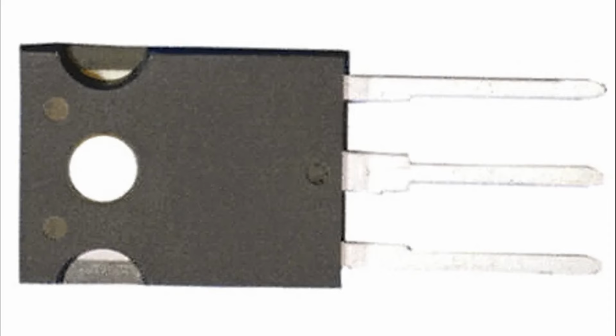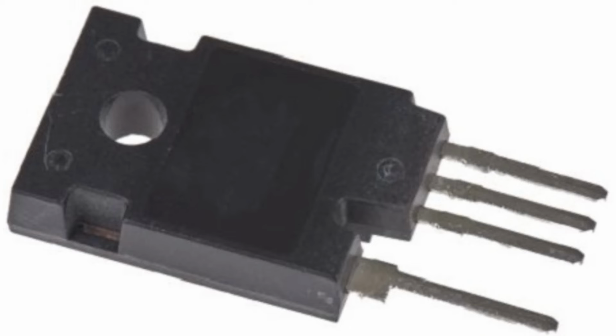2. Control mechanism. The gate voltage controls the operation of the MOSFET. Gate voltage, V_GS: the voltage difference between the gate and source terminals. Threshold voltage, V_TH: the minimum gate voltage required to form a conductive channel between the drain and source. The threshold voltage is a crucial parameter that determines when the MOSFET turns on.